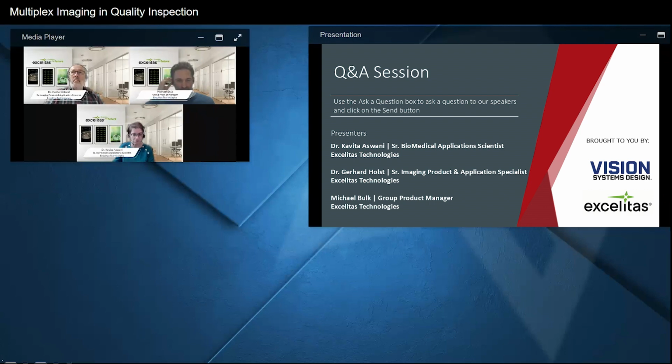Is quantum efficiency the only important parameter in low light imaging? Well, I don't think so, but it's a major one, because if you're going for multispectral, then in general, first is you will have to have a detector that is suitable for the application. Second is, since in many applications and with different filters, there might be a larger difference in the signal quantity, and therefore I would say a larger dynamic range can come in handy.